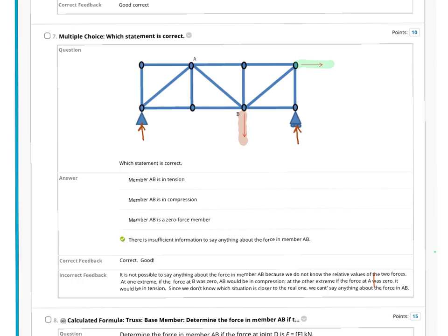But for the horizontal forces, if you consider the reaction force direction, this side it would be upward, but that side it would be downward. Why is it downward? Because if you take moment of these horizontal forces about this support point, then the reaction force on the left hand support must go vertically downward to compensate the moment due to the horizontal force.